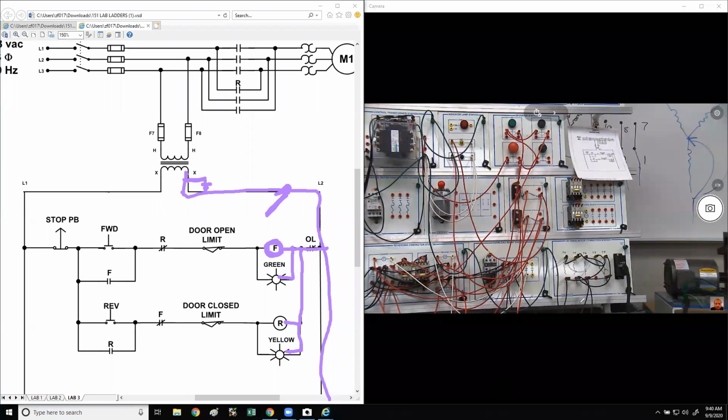In order for that motor to start running, we need these 3 contacts to close, right? And that's controlled by this. So if this is your output and we're working back, what's the first thing we should check? Limit switch? Nope. Is there still a chance that this forward coil is bad? There's a chance. Yeah. There's a chance that the forward coil is bad and the green light is out. Okay, but we definitely want to see, do we have 120 volts right here at the forward coil?